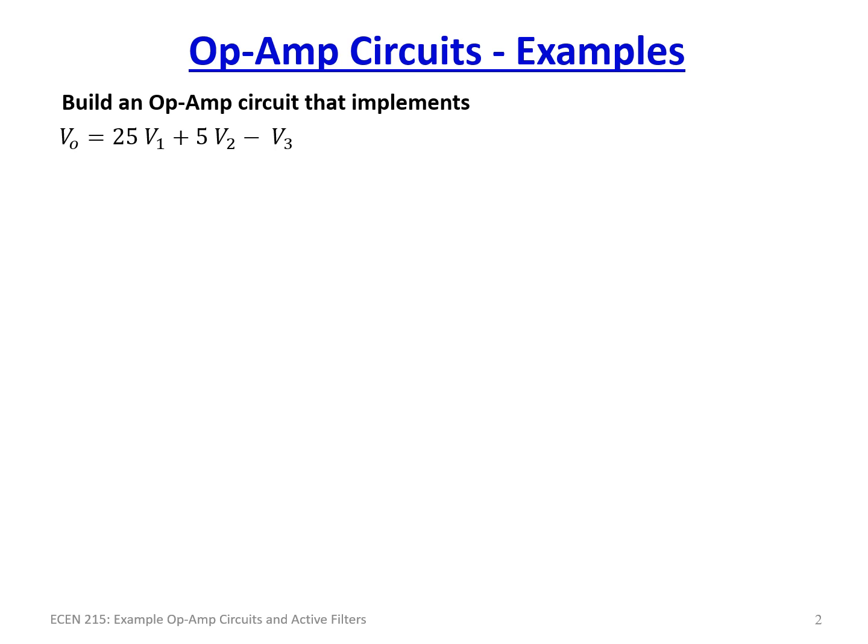So V out would be equal to minus, with some gain RF over RN for that stage, V1 minus V2 minus V3. So it's summing the inverse of the inputs. But that's useful because if we put an inverting amplifier in front of that, we can flip the mathematics around. So the first thing we need to do is set that up.